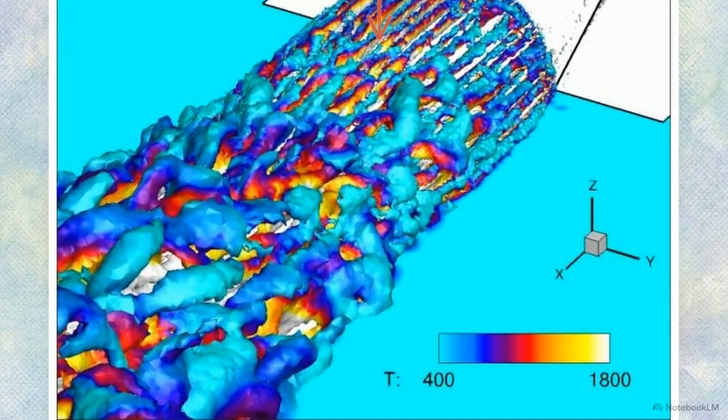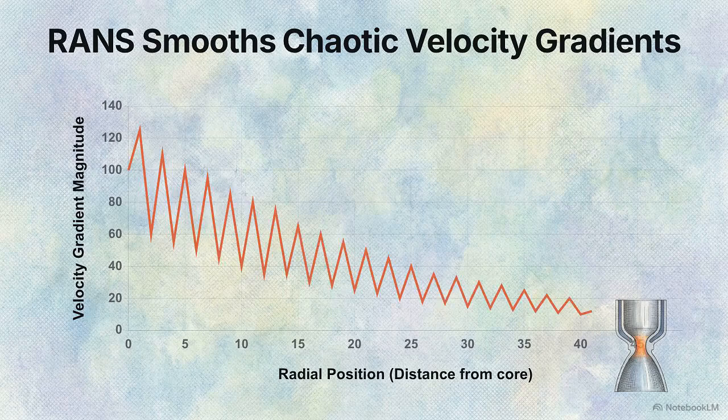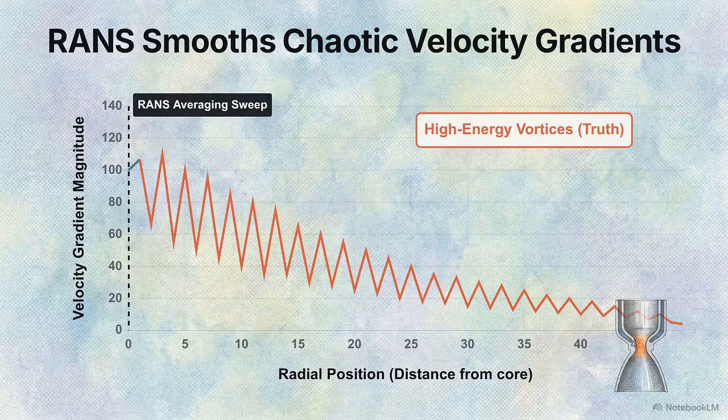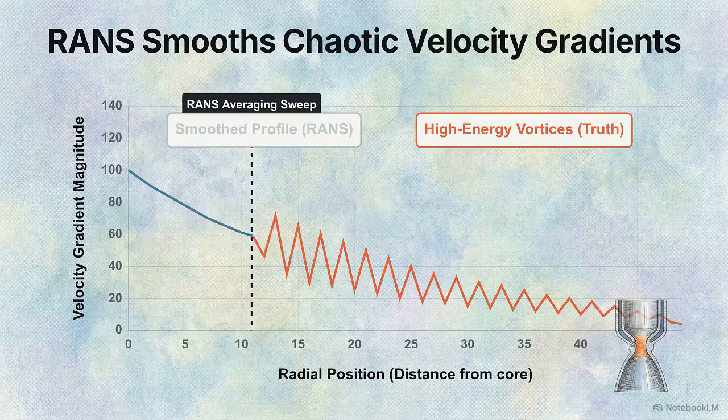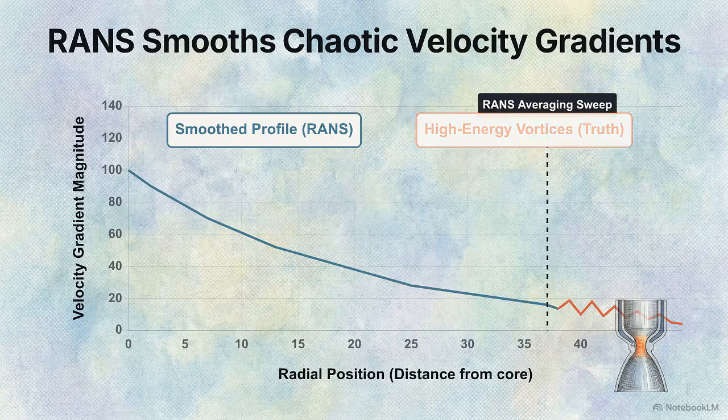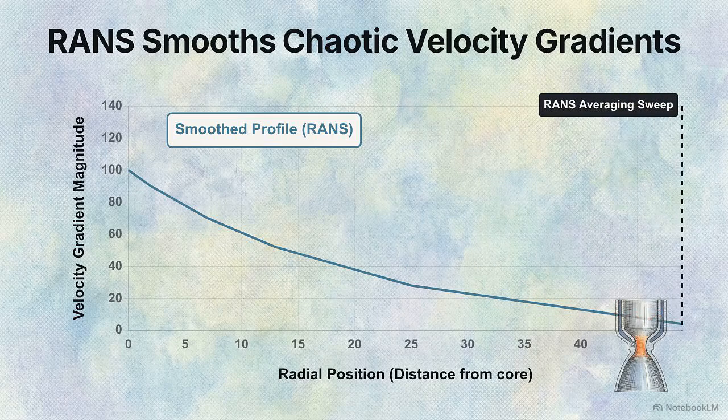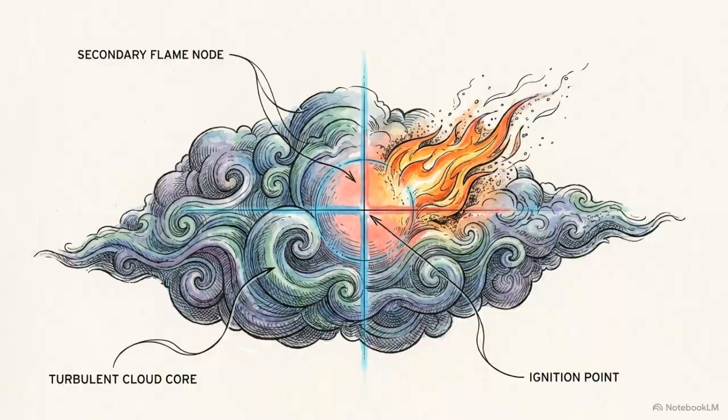This specific interaction triggers the first major flow fluctuations in the plume. A 2D axisymmetric RANS model smooths the velocity gradients radially, preventing these defined longitudinal vortices from forming and suppressing the mechanism of their breakdown.